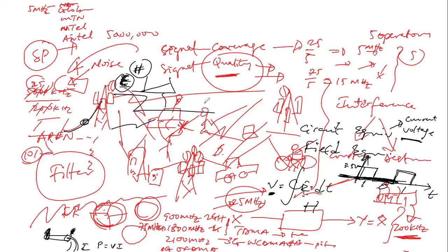So when we talk about the plane of polarization, how you should align your antenna for reception of this signal: if I have horizontal polarization, it means my antenna is horizontally placed, so the E field is going to come out in that horizontal manner. So the receiving antenna must also be horizontally polarized, or vertical. But in practice, we are not dealing with that.